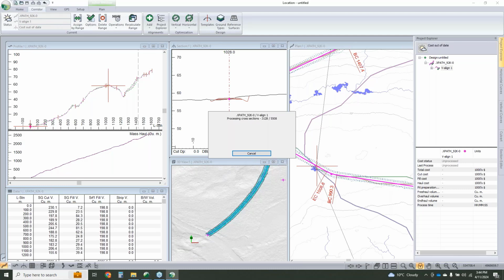Totally. And then I might just quickly recap what you just did in the last 10 minutes. So Matt loaded up a terrain, brought in his project data, figured out the preliminary location for 2 sections of road between some turbines, brought it into location, turned it into an alignment with curves, which wiped out his profile. And now what we're waiting to solve is that optimized profile.